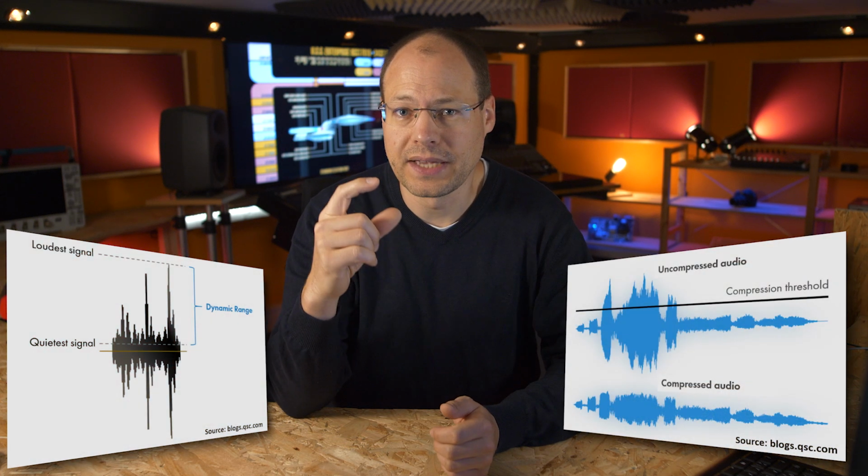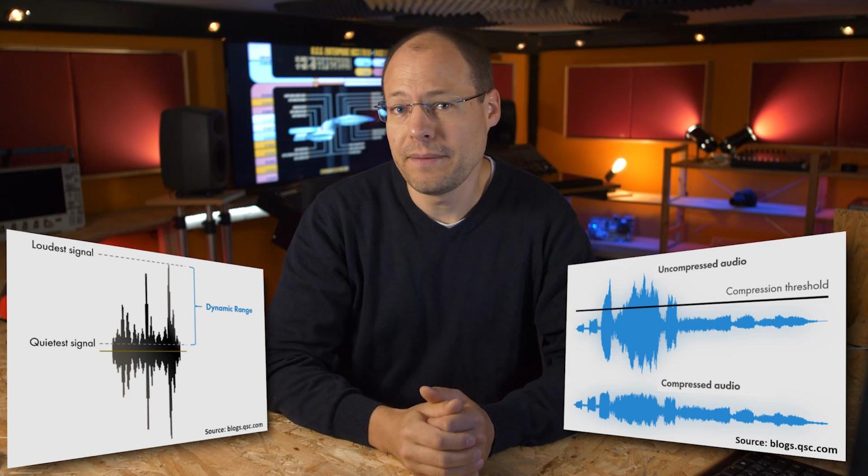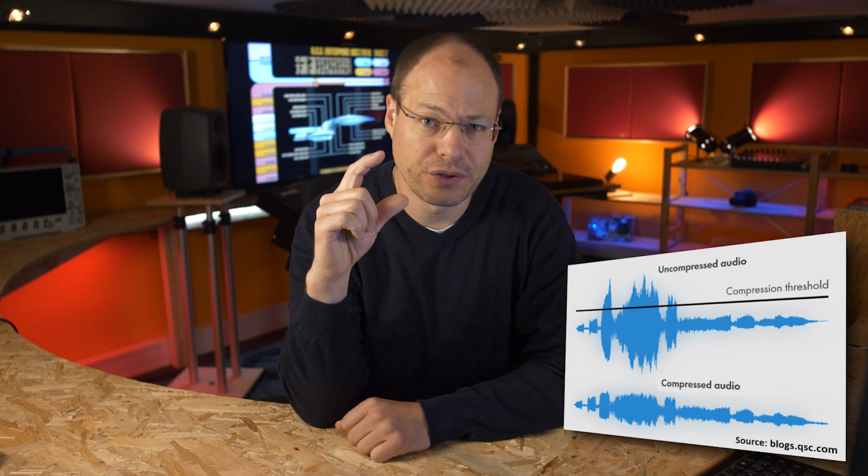However, this is still not the typical sound that we know from today's audio recordings. The missing magic words are dynamic audio compression. This automatically reduces the volume of audio samples above a certain threshold. The level of compression can then be set via the ratio. As the audio signal loses level with stronger compression, the volume can be increased again using an additional gain called makeup gain. What exactly do we need to implement this now in the FPGA?